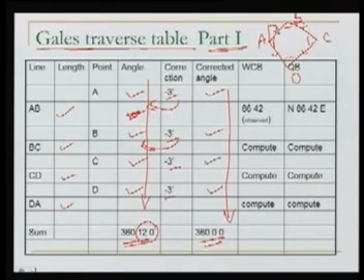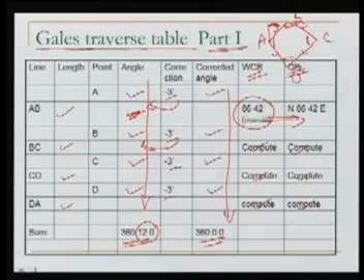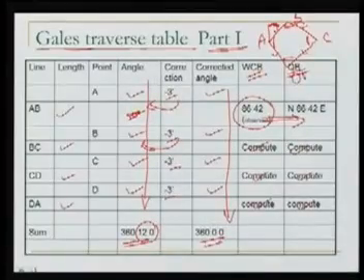We have measured the bearing of one line here, line AB. Using this bearing which is observed, we can compute the bearing of other lines because we know the internal angles. So this we have done, we already know it, how to compute it. Well, we convert this whole circle bearing in quadrantal bearing. So this can be converted to the quadrantal bearing like this. And similarly, others can be also determined. Now why we convert it in quadrantal bearing? Because in order to convert the length and the bearing of a line into the corresponding latitude and departure, we need the quadrantal bearing. So using that we can compute easily. So this is why we are converting it here.